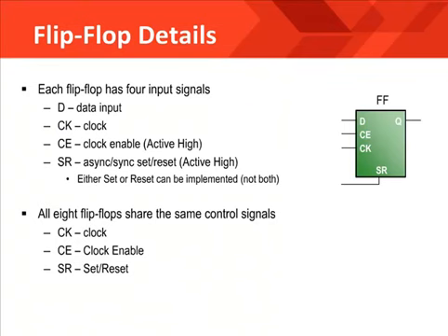You have to remember that the clock enable and the set reset ports are active high. This is important when coding your HDL for the flip-flops. Likewise, note that there is not a separate set and reset port, just one port that is either set or reset. And this port can be asynchronous or synchronous.